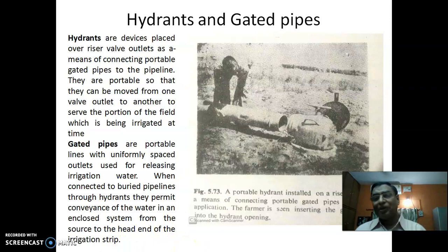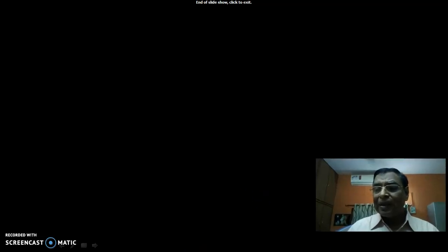So altogether, I think that is the end of the presentation. Yes. What I feel is, we have seen the underground pipeline irrigation system in two videos. One stressed the need for an underground pipeline irrigation system to save water, and then the various elements: starting from the pump stand, air vent, and then of course gated pipe, valve, and then riser, and then the hydrant which we fix, and all these things.